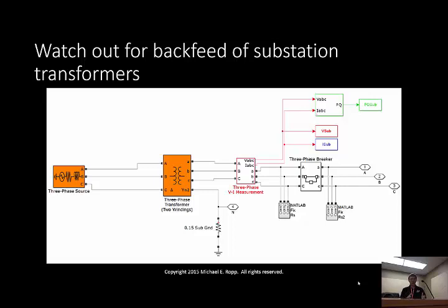But we've got this transformer set up with the substation ground grid. Right now we've got 150 milliohms of impedance to remote earth in the ground grid. But the point of all of this, you notice there's that three-phase breaker over there. That's my feeder breaker. If that's the one that isolates, then I'm worrying about the circuit downstream. But what happens if I have a single-phase to ground fault between the two orange blocks up there?